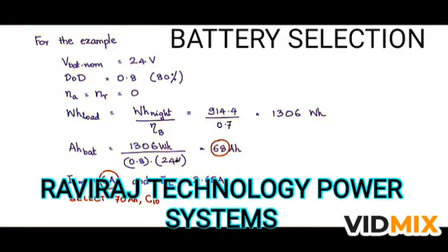This is a worst case design in the sense that you are seeing to it that even the maximum current rating is within the C10 rating. The capacity is preserved, but this will result in a bigger size battery and costlier battery. However, we could also go a bit more conservative in the cost by choosing the 68 ampere hours and the average current 2.65 amps.